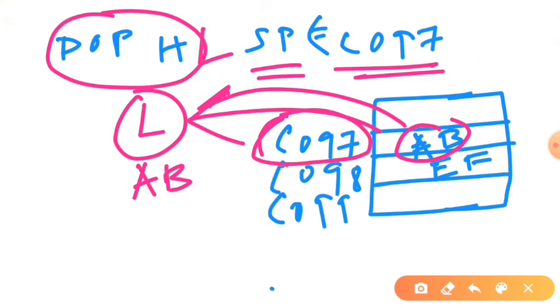So we must understand it right now. Okay, the higher order byte is always stored in the higher memory address, the lower order byte is stored in the lower memory address. And as you can see, C098 is higher than C097, so C097 obviously should contain the lower order byte. So it's easier to remember, and it's also the convention. So you go by the convention, it will be easier for you to remember this. You'll never get confused.